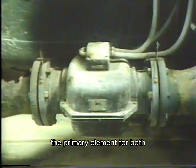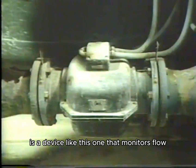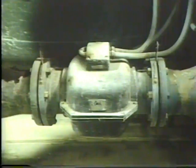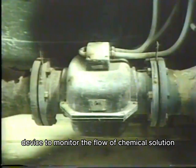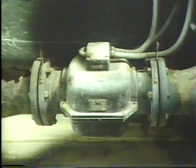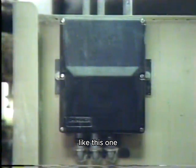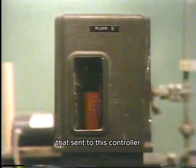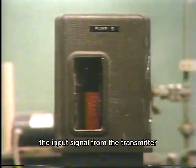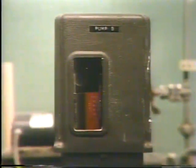The primary element for both the water and the chemical variables is a device like this one that monitors flow. This process has one flow device to monitor wastewater flow and one flow device to monitor the flow of chemical solution. The signal from the wastewater flow sensor goes to a transmitter like this one. The transmitter converts the flow value into a signal that's sent to this controller. The input signal from the transmitter provides the set point for the predetermined ratio that this controller maintains.